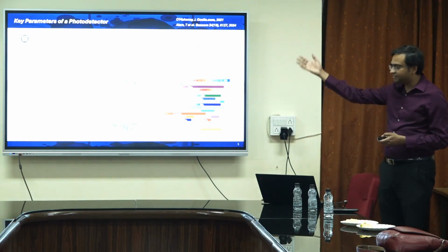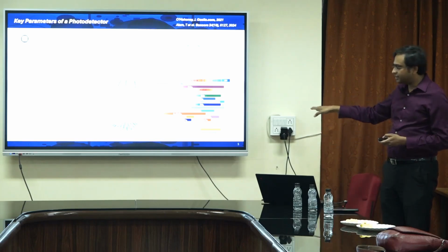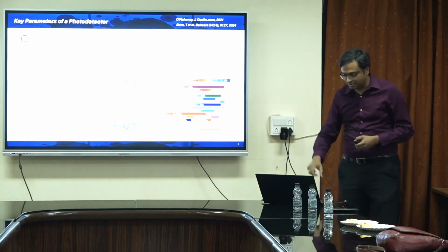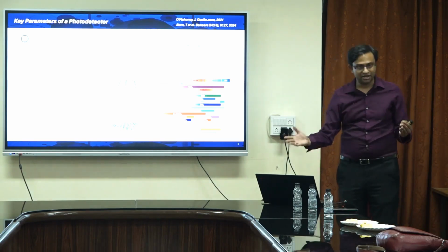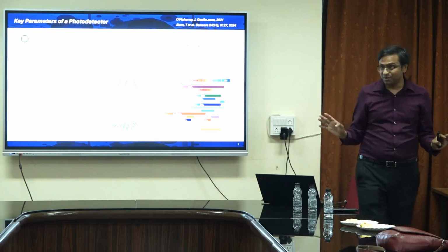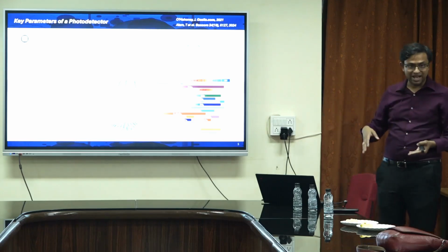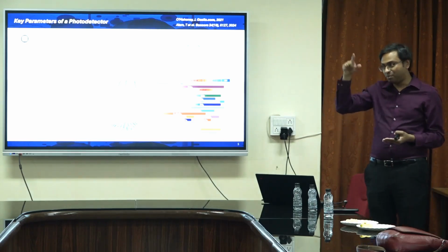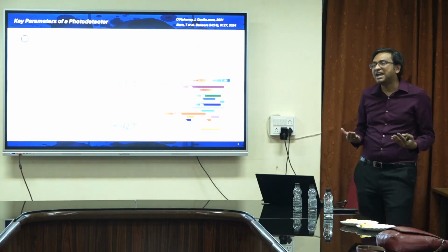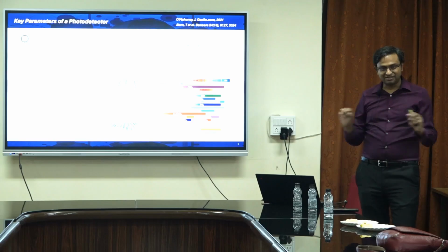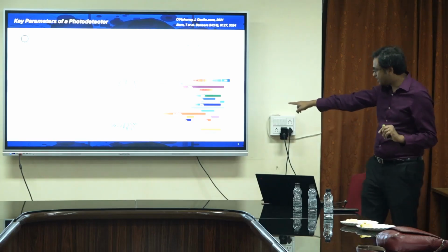And you can see even within the 2D material family, graphene, for example, is actually very interesting. It's broadband. That's another amazing property of graphene, because it does not have a band gap, and it's a direct cone. Every point is a direct band gap. So it can literally absorb light of any energy. So that makes graphene a broadband photodetector.